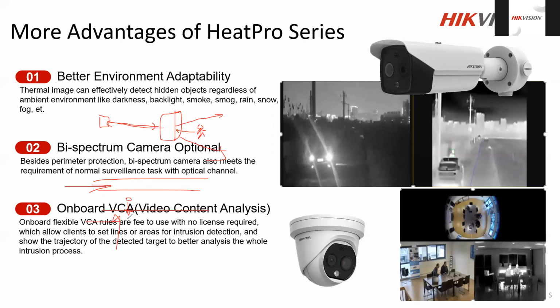So there are two ways to answer this question. One is that it cannot measure the temperature passing an obstacle, but for a fire prevention scenario, first you can detect smoke. Second, you can detect once the temperature reaches the surface. Those are the two things that we normally suggest. And when we are doing a project installation, we recommend 2D coverage, so there is more coverage to read the surface temperature.